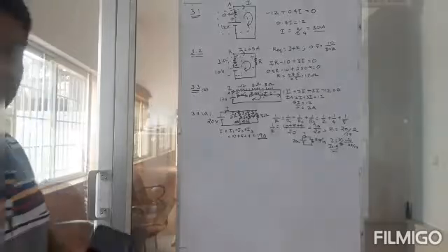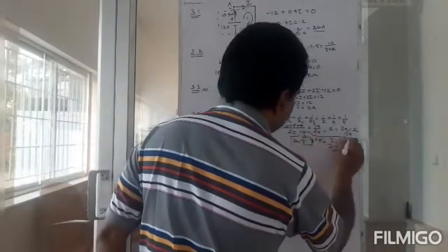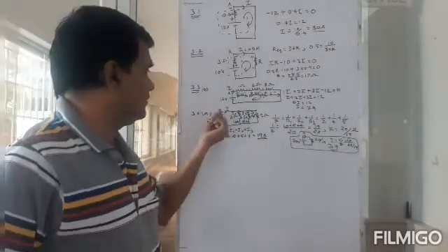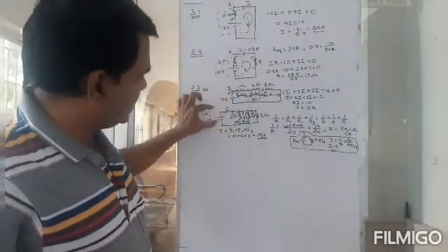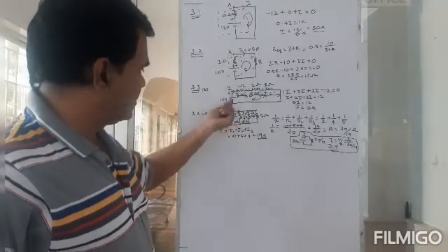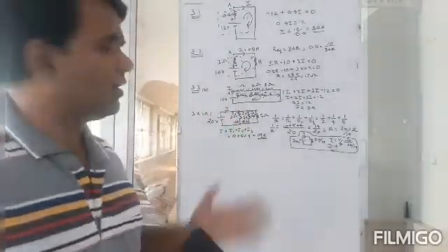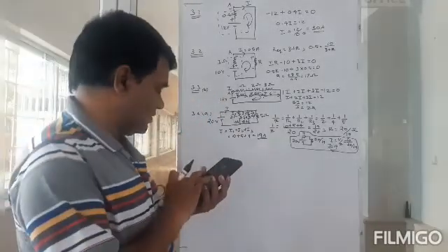Okay, so either way you can do it. There are many ways of doing this. So one of the ways, I'm saying, the total current can be easily found by finding the effective resistance, or I can take this resistance. I know 20 volts is applied across this, so then I can find the current through each resistor, or I can use Kirchhoff's laws to do the same thing. Yeah, that's the same stuff.